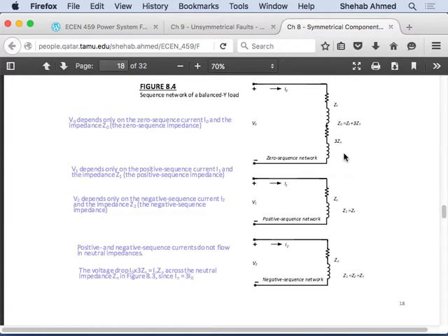Current leads to flux in the air gap, leads to a certain amount of armature reaction, leads to a certain value for synchronous impedance, if you remember from the 338, right? The inductance is, again, you have currents in coils and magnetic fields around them. So if the value of the current is very large, the value of the inductance will change, right? You remember L is equal to delta lambda over I, from 438 or from our discussion in this class when we were calculating the inductance. It depends on the amount of flux, so it will depend on the amount of current.